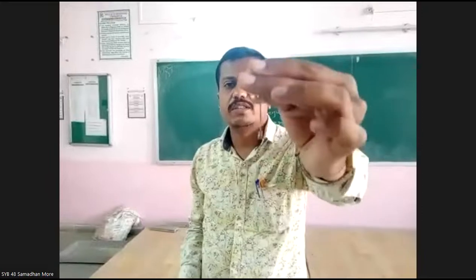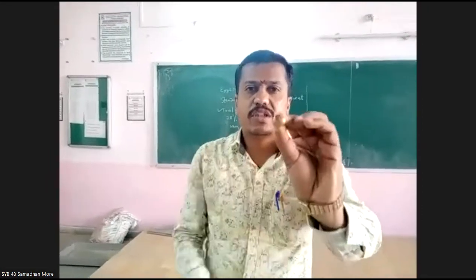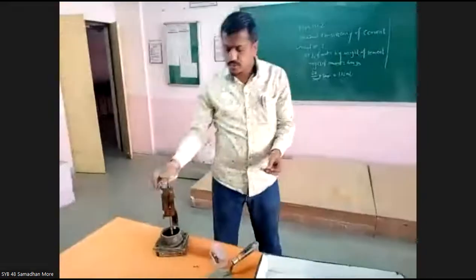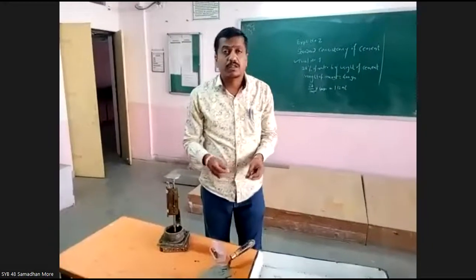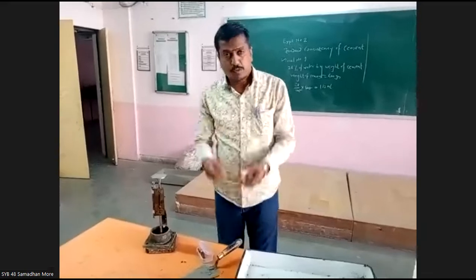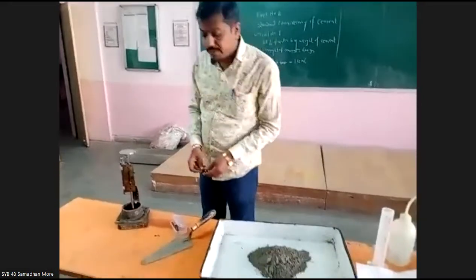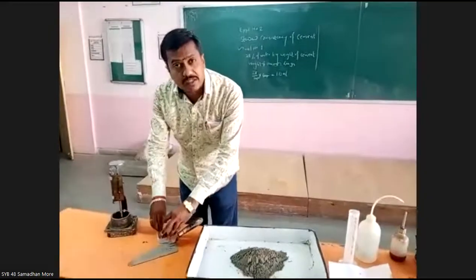And this is your final setting time needle. As you can see, this is your final setting time needle. Here, some impression is there. Okay. Again, you are going to attach these 2 needles to this apparatus, and then you are going to check the setting time of that particular system. Okay. But before proceeding, let us rewind our previous practical. Let us take the second trial. That is for determining the consistency.